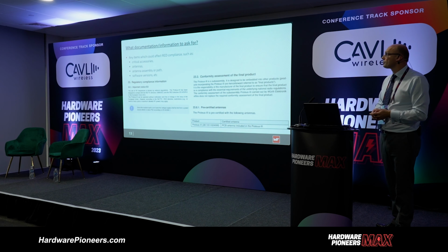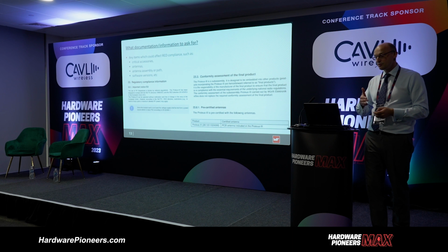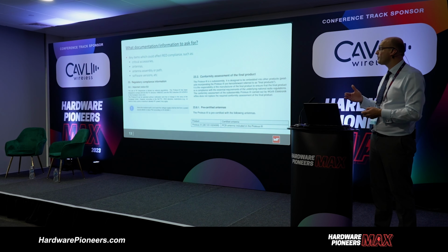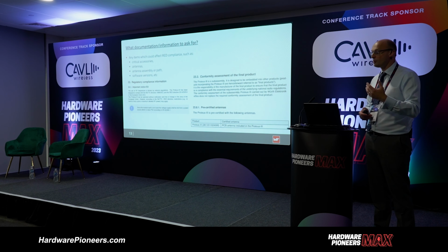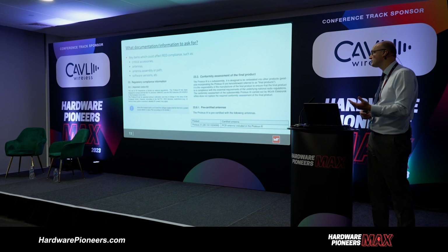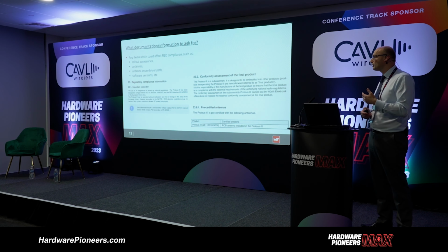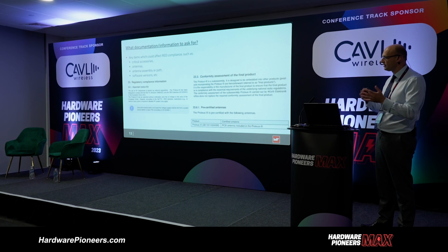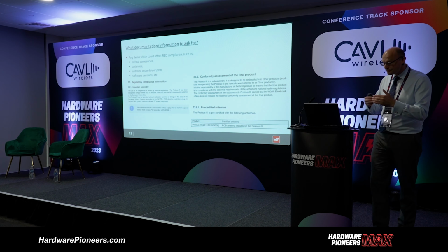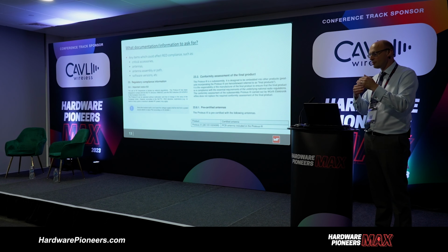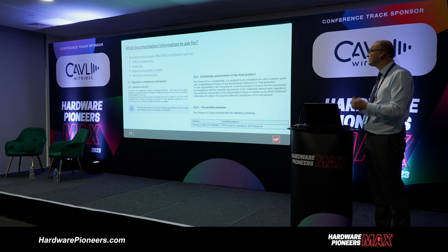Changing the antenna assembly or the antenna path. Certainly the antenna path becomes more critical if you are putting it into the American market. FCC are very, very specific that you use a particular layout with regard to the actual antenna matching.